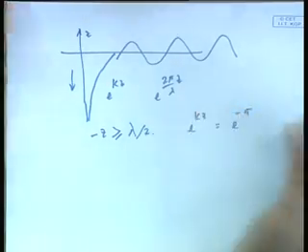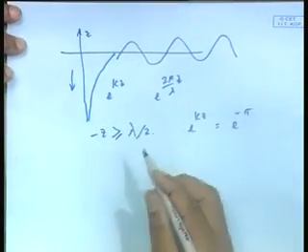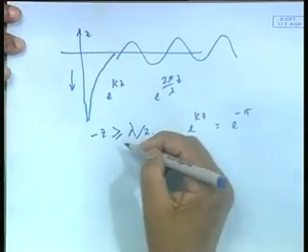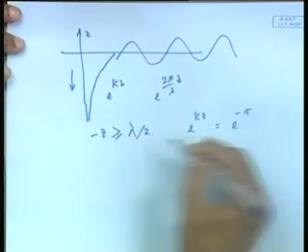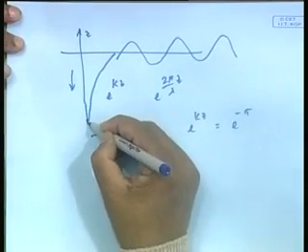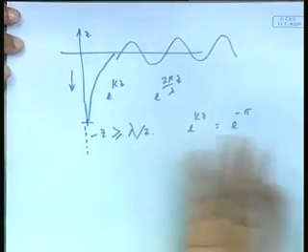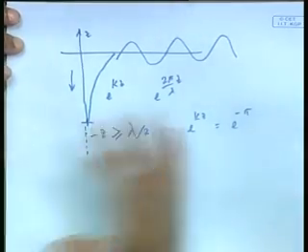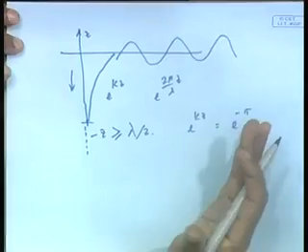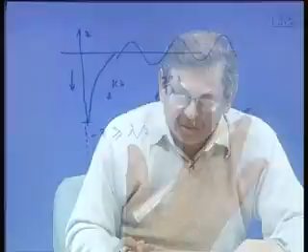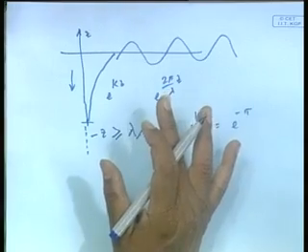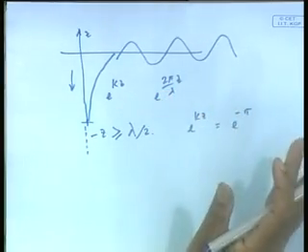So, the rule of thumb, which is how this word came, is that if the water depth is more than half the wavelength, then anything that is happening below that is so small, almost 0, that you can ignore it. So, we say that if the water depth is more than half the wavelength, we consider it to be deep water, or a deep water case.